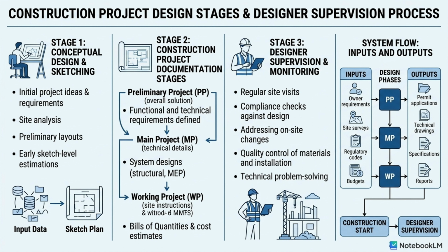Stage 1 is conceptual design and sketching. Here the initial project idea and requirements are gathered, and site analysis is performed to understand the context and limitations. Designers prepare preliminary layouts exploring different solutions and produce early sketch-level cost estimations. This phase turns data such as owner requirements and basic site information into a foundation sketch plan.